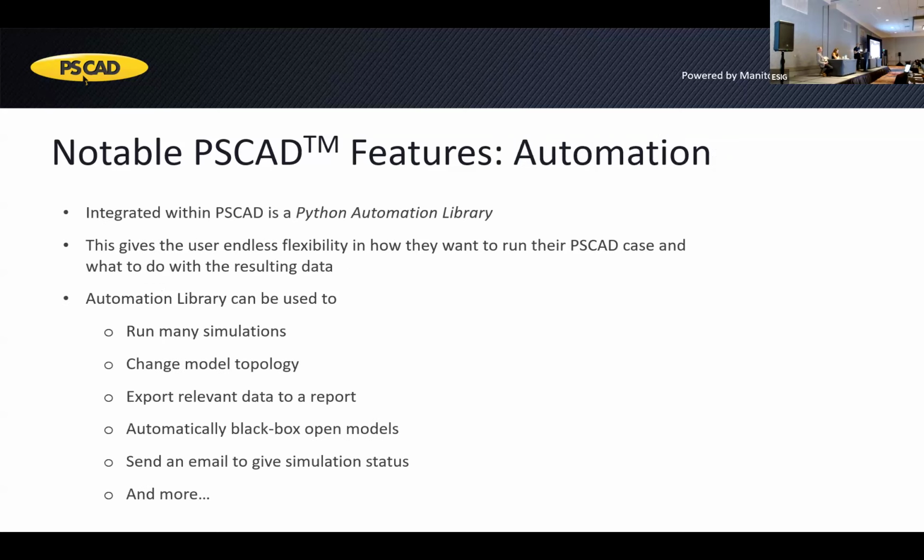The next is automation. Someone had mentioned it in a question, and yes, PSCAD does have a very extensive Python automation library. This gives the user endless flexibility in how they want to run their PSCAD case and what they'd like to do with the resulting data. The automation library can be used to do things like run many simulations, change the model topology, export relevant information to a report, automatically black box any open models, even send yourself an email to give simulation status on a simulation that you're running.